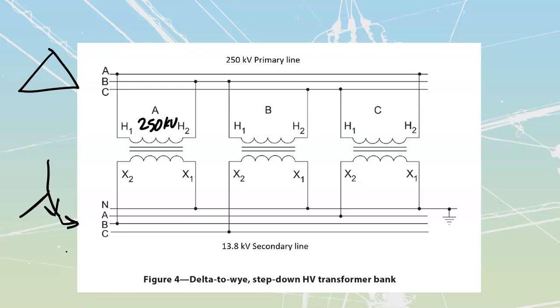We'll go through these calculations as well. Once again, it is going to be 10 MVA that we will start with. For each of these, 10 MVA. And 10 MVA and 3 transformers is going to get me to 30 MVA. That 30 MVA, we're then going to be able to divide out by our primary values of voltage and our secondary values of voltage to figure out what we have for our line currents.